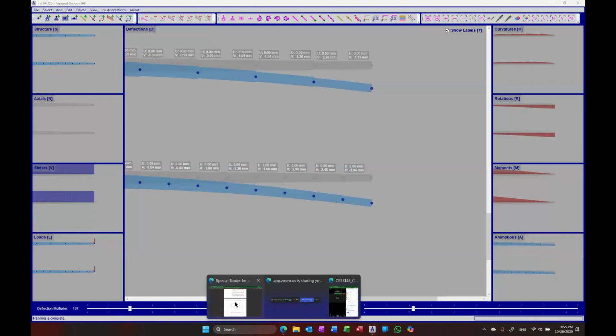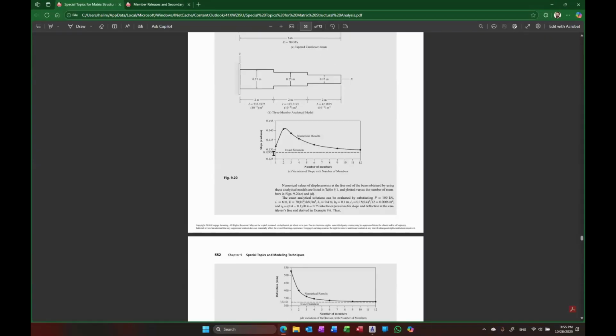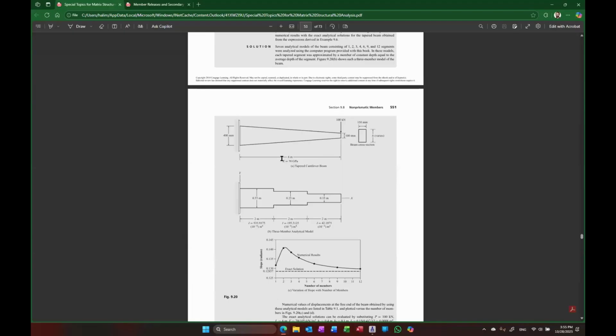I believe that is also what is observed in this case study here. So yeah, it goes up first and then slowly comes down. This is slope, but yeah, so depending on how you choose to divide and which sections to pick, you will have a different behavior. In this case, I think they never used the largest section. They're basically dividing it and then finding the middle point of each section, and then using the section properties in the middle of that section, which is probably a smarter way to do that.